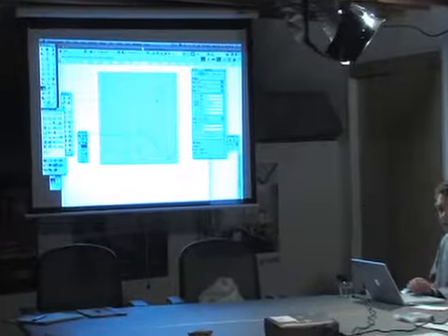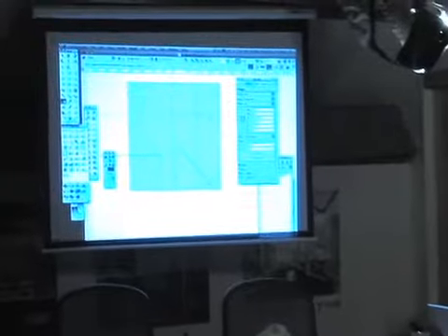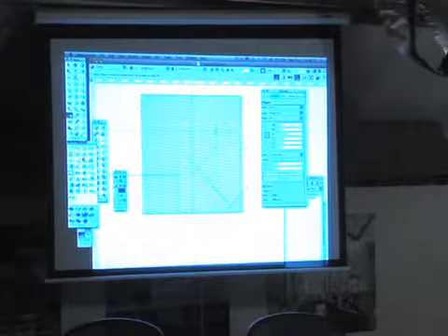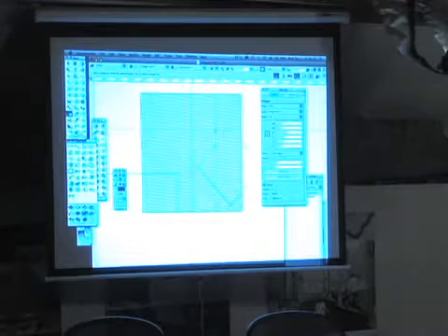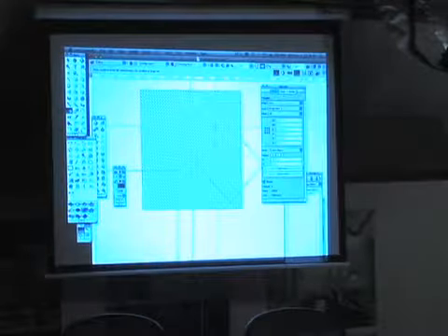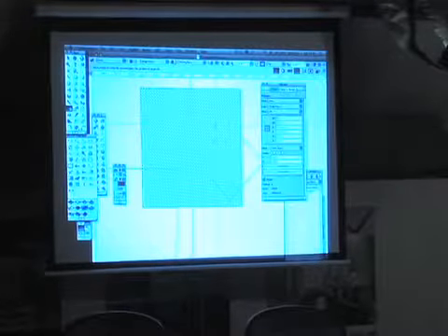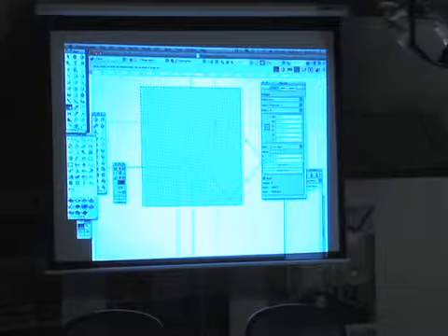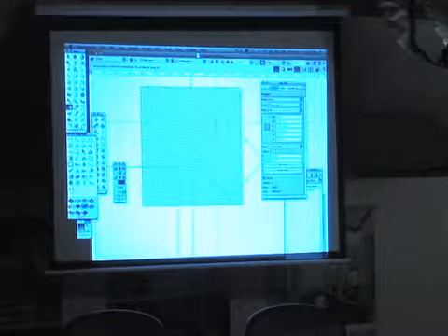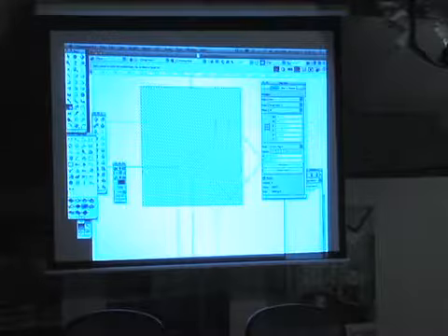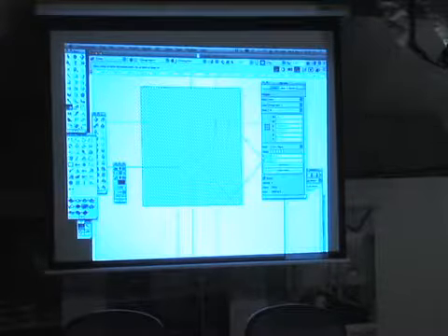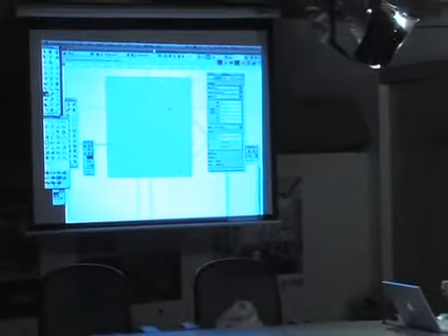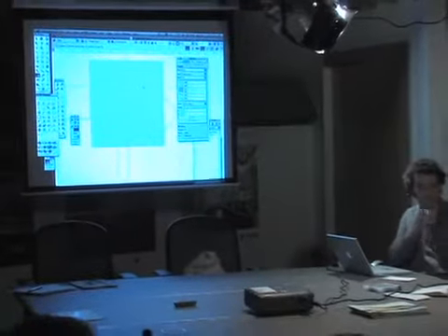If you start a hatch, it will go from your origin on the page, 0,0. So if your drawing or elevation happened to be at a certain point on the page, then you couldn't control where your brick started, unless you applied it to that object and it turns into a group. Yeah, then you have to do it that way, and then you lose the interactive. You have to go back and fix all the lines, and that's annoying. One of the things they said at the road show thing they did a few weeks ago was they're actually moving toward doing away with hatches.